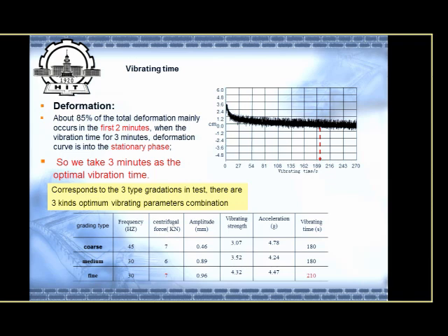From the test result, we can get the best compaction parameters. For the 3 gradations, we have 3 different kinds of best compaction parameters.